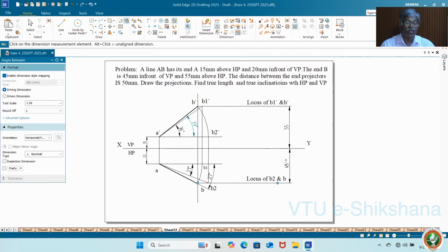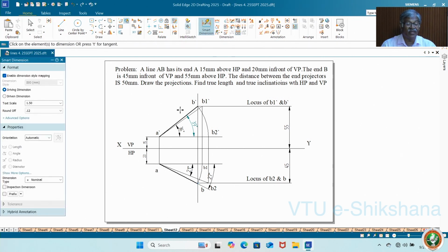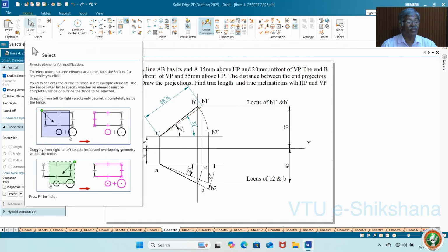So this is how you can work a problem on straight line and get all the information. Now finally, how to complete the dimensions and all? See, this is how you come in. Because true length is not given, you are going to obtain true length. So both sides you must get same thing. Hope that you'll get. Yes, there is small change. 68.74 is the true length approximately.